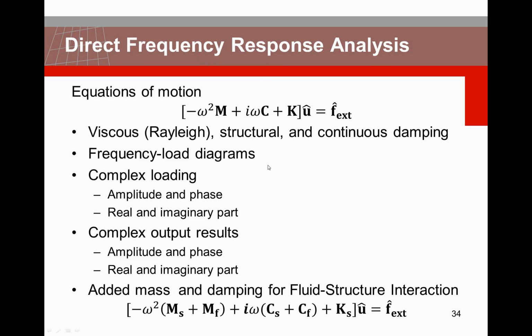It's complex. What is important is when you compare a direct frequency response analysis to a modal frequency response analysis in the sense of calculation time, the direct frequency response analysis needs much more calculation time. That is because this complex equation needs to be solved for each excitation frequency omega.